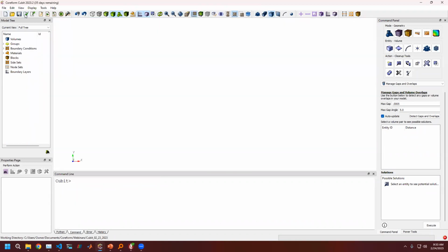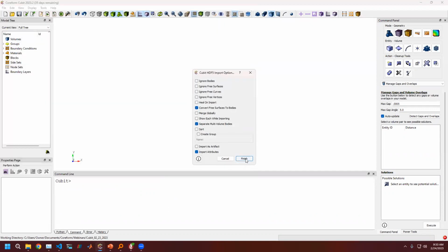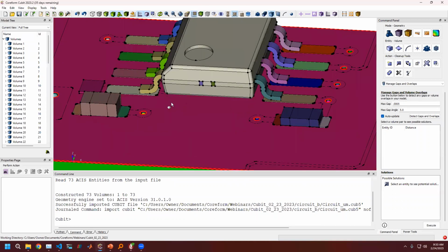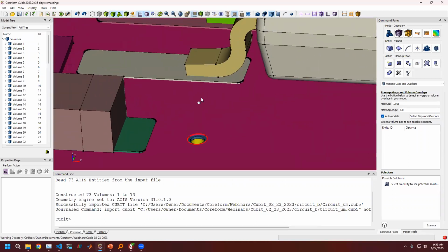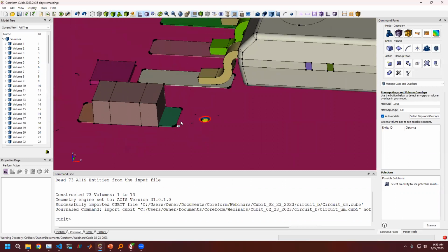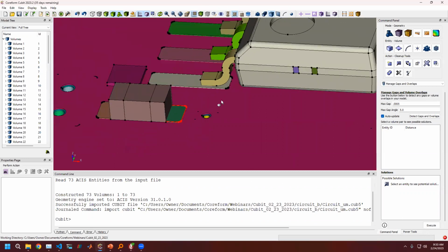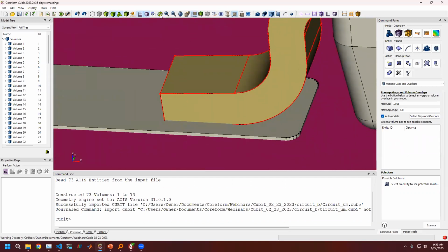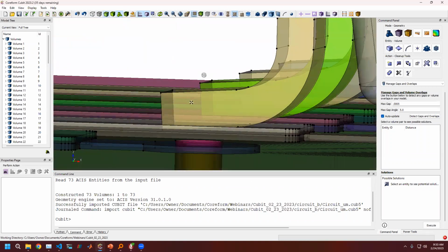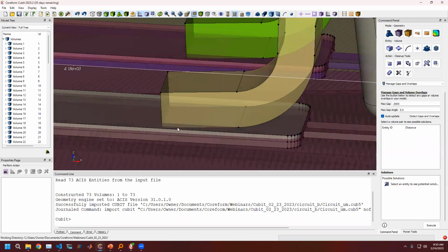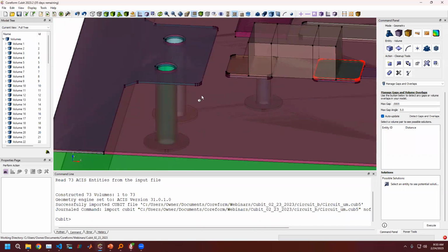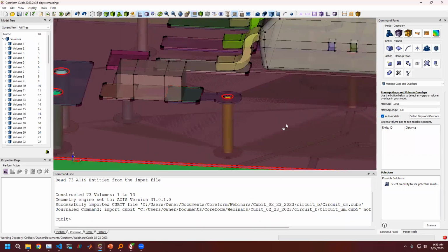Actually, no, I want to do the micrometer one. So again, this is something that I maybe have scaled by a factor so that my small length or small edges are far away. This is another model that was auto created by, in this case, Fusion 360. And one of these you can see is that I've got some significant overlaps on these legs on their pads. And again, I want to get rid of those overlaps. And we have that same exact issue with the overlaps of the different traces on our model.